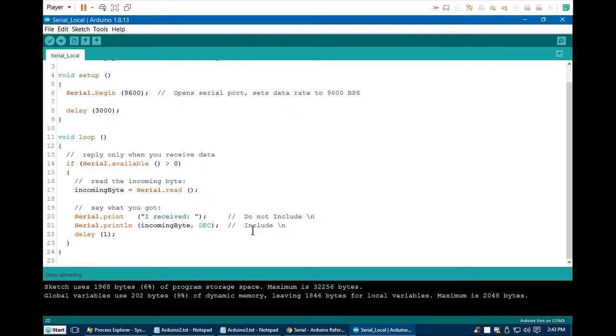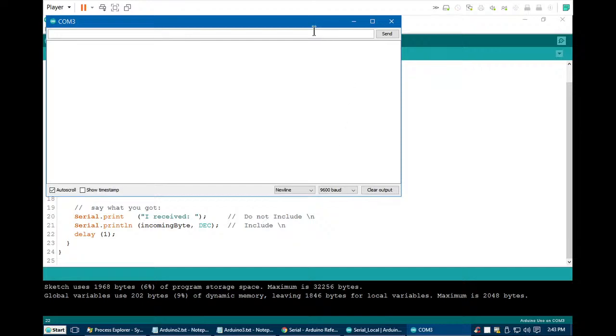So the first thing the program will do is initialize the serial terminal. In the Arduino, the serial terminal is built into the Arduino IDE. So if you go to here, this is the serial monitor or the serial terminal. You click. If you see the color of this window is active, blue, that means the connection between the Arduino and this monitor is connected.